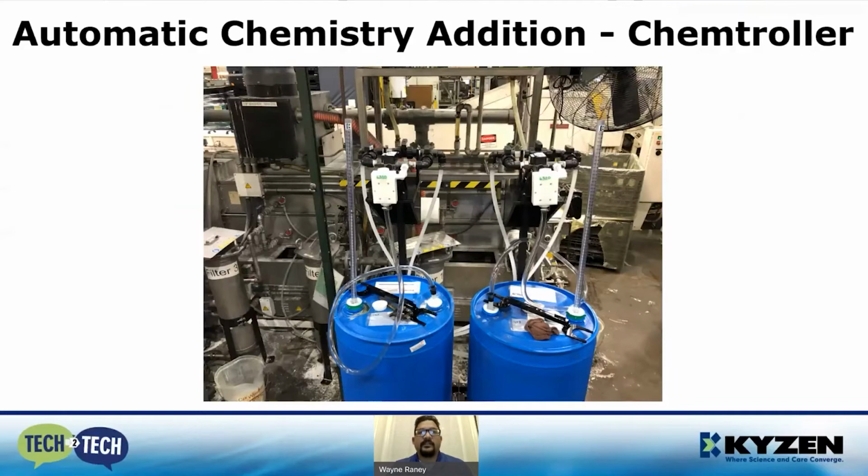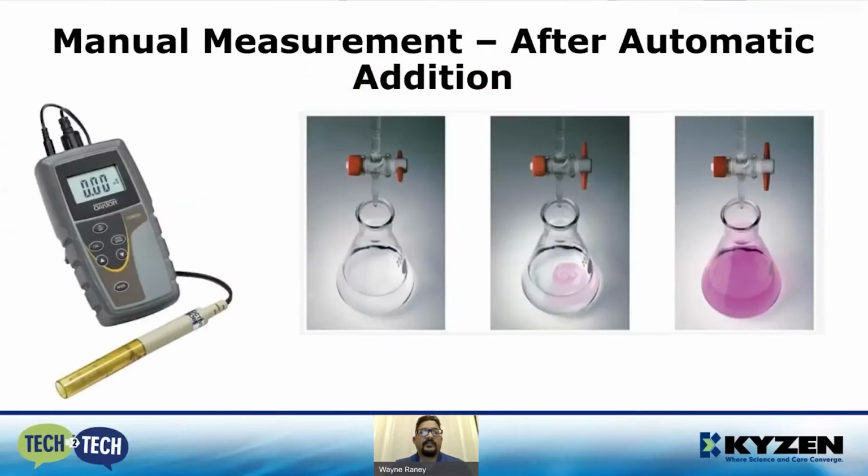Even though this automatic dosing system is automatic, it still needs operator interaction. So there is a certain amount of drift associated with the setting. So this is where the operator once again has to check the concentration by way of conductivity or titration. When first implementing the process, I suggest checking the concentration at least twice per shift until you get the handle on changing the knob position, how it affects the concentration in the wash tank.